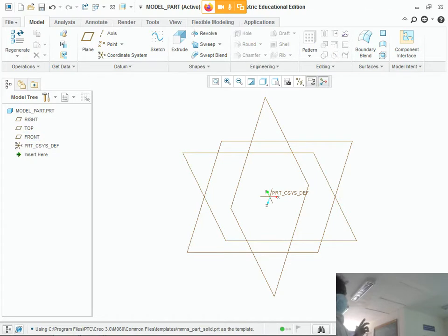And then you also have the other options. What you have to do is, we are planning to create a square sketch, and then we wish to extrude and make a cuboid or cube out of it. Right now we want to create a sketch. So before you create a sketch, you can choose the plane on which you want to draw. Anything you can choose. Say we are choosing front.